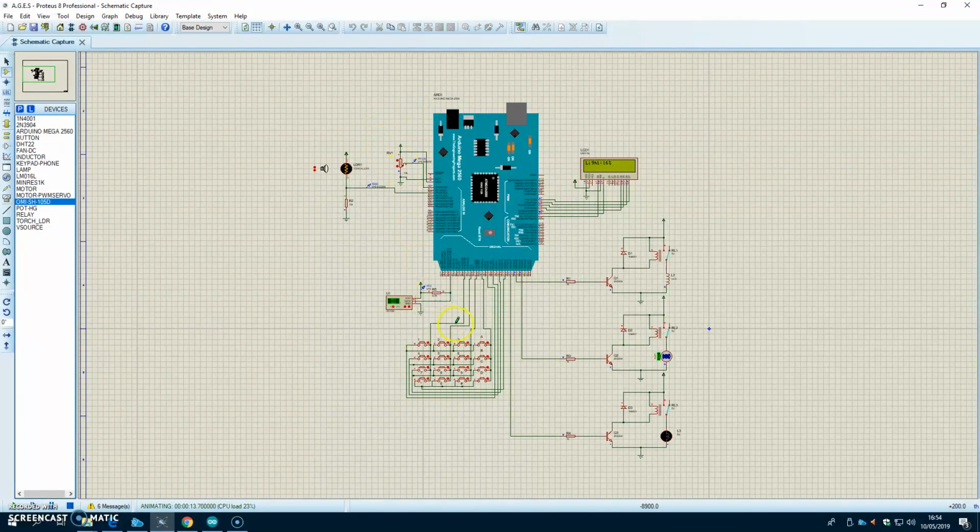So the variables have been stored already within the EEPROM, just for simplification of the code, so of the video. So if I just drop down the light, as you can see, I can manipulate the amount of light being shone on the LDR. The closer the light, the brighter the reading of the light on the display. So you see right now it's showing 95%.